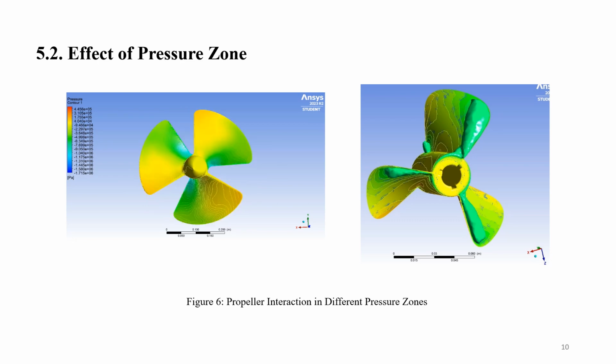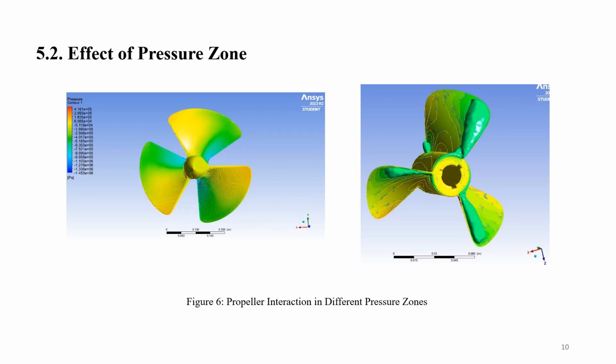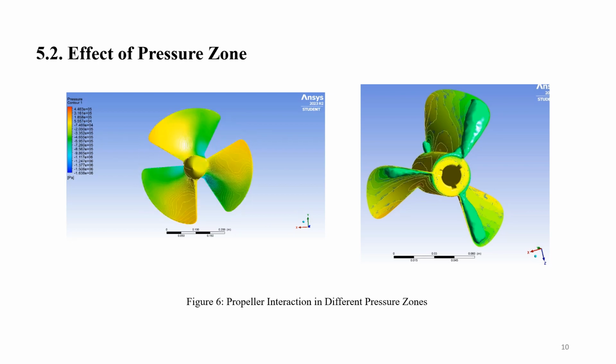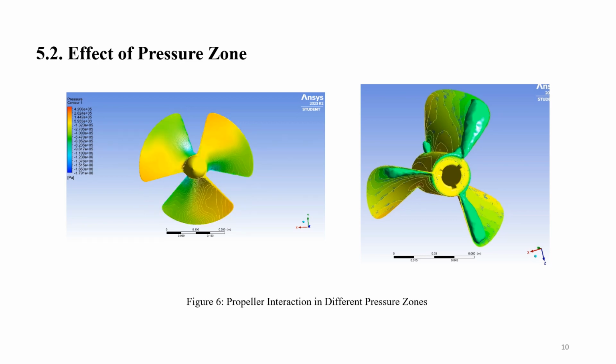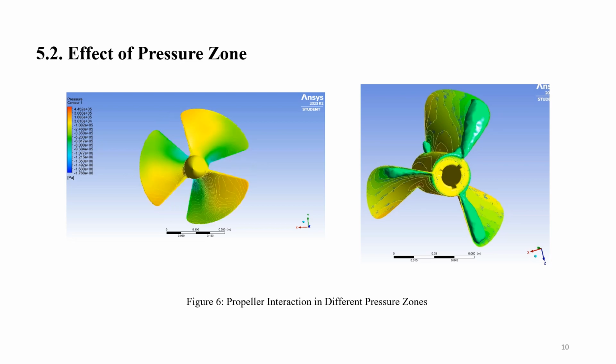By keeping the same boundary conditions in both of the propeller cases, to understand the effect of cavitation, the updated propeller model has been simulated transiently, where the propeller has been operated for 7.5 seconds at 900 RPM. As the water temperature in the simulation is 25 degrees and the vapor pressure of water at room temperature is 3.17 kilopascal, all the negative pressure zones at the trailing edge during different times show the phenomenon of cavitation, as seen in the pressure at different time stages.